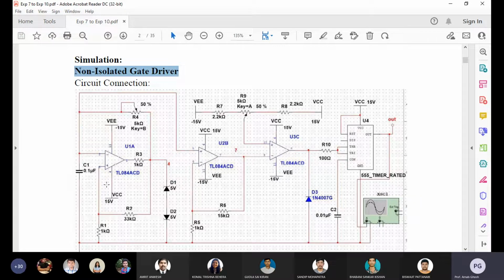That's why you can see it starting with 2, 3, then 5, 6. Pin 1 is the output of the first op amp, 2 is the inverting terminal, 3 is the non-inverting terminal.